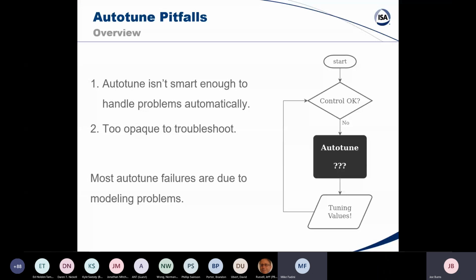I've got a question for you there, Joe. What are the pros and cons of open loop versus closed loop? Well, feedback control, closed loop control, is a pretty magical thing. It really makes everything a lot easier, and that's kind of why PID control is so ubiquitous. Open loop depends on your plant basically being the same over time, no changes.